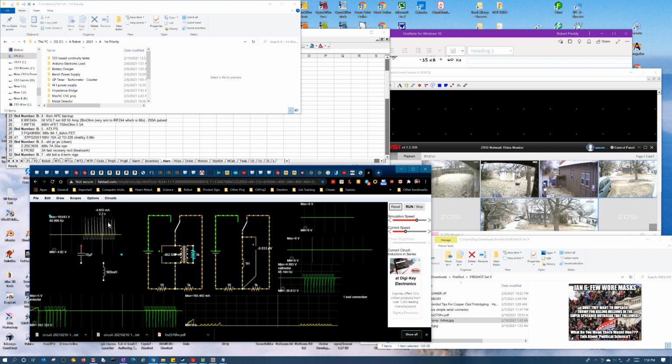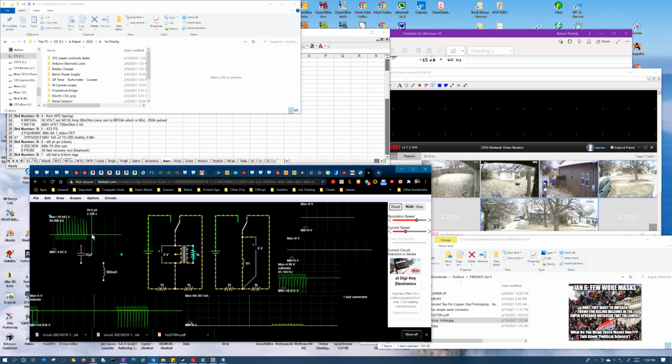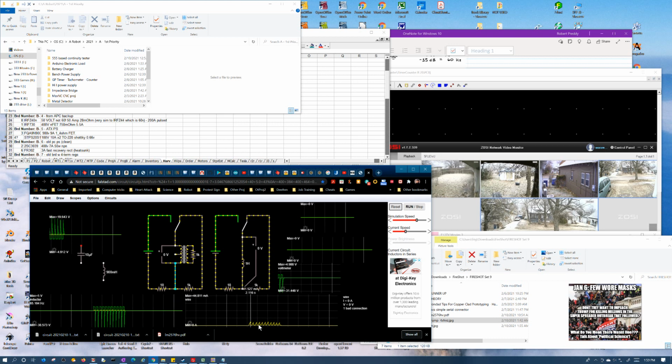So that produced a 19 volt spike because I was switching it fast enough, and certain power supplies work that way. Some switch mode power supplies work that way. The current in the inductor goes down almost to 0, if not 0, from that.